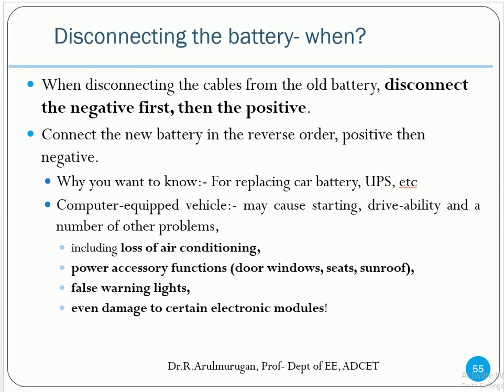How to disconnect the battery? Always disconnect the negative terminal first. Why the negative terminal first? So that you avoid a short circuit. That's why you always remove the negative terminal first, and when you connect the battery, connect the positive terminal first.